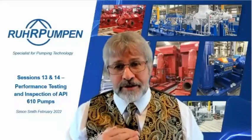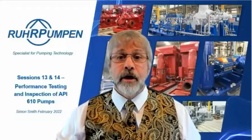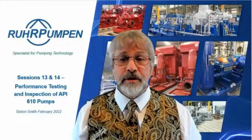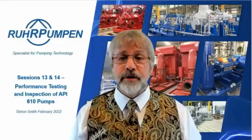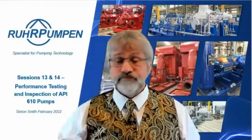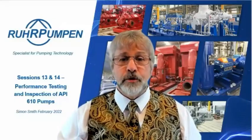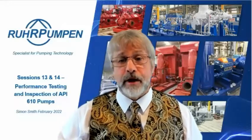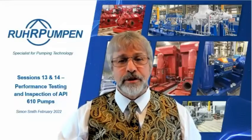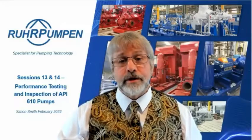But as I said when we were looking at complete unit test, if you are dealing with a multi-million piece of equipment, then yeah, I can well understand why you would want to have complete unit test carried out to check that everything works. But it's very expensive. Do you really want to do that on standard pumps? So I would push back on standard pumps and say, no, it's not economically viable to do that. And it takes a long time. A string test will probably take a week to set up.